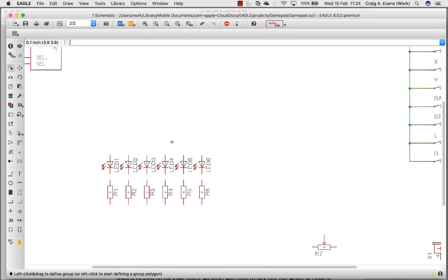So we'll do the LEDs using a similar process. These are going to be active low, like the onboard K64 LEDs are. So the anode of the LED will be connected to 3.3 volts, and then we'll go to the current limiting resistor, and then this side will connect to the pin. So we make the LED come on by making the pin low.